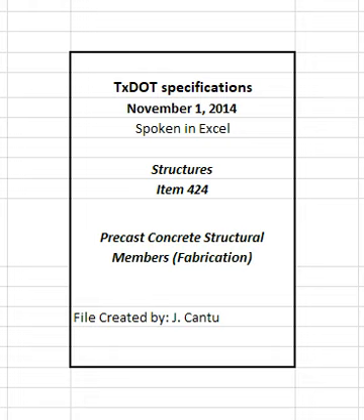4.1.2 Plant approval. 4.1.2.1 Plant submittals. Provide submittals in accordance with DMS 7300, precast concrete fabrication plants, for each particular plant operation. This requirement does not apply to project-specific non-stressed member fabrication plants. 4.1.2.2 Plant audits. Multi-project and project-specific fabrication plants must pass initial and periodic department-directed plant audits in accordance with DMS 7300, precast concrete fabrication plants.